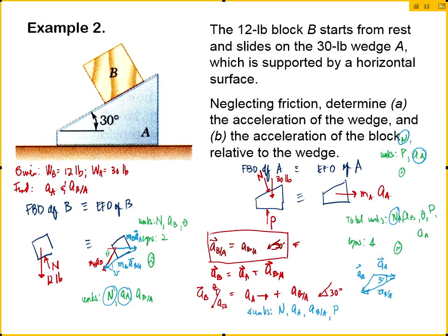Not necessarily. That's the dangerous thing. Some of you will say the total normal force from the ground is just the sum of the two weights, and that's not true. Because there's motion now. You're again saying in your head that the summation of forces along the vertical is 0 for the FBD of the two. That's not correct, because B actually has a net downward acceleration.